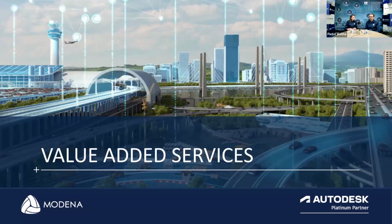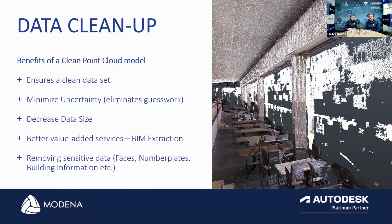If I can just add on that part of cleaning in Recap specifically: when you remove point data, for example if someone's face was scanned, when you remove that information you save, you can update the photographs as well to completely remove that from the data. So not only the laser scan data, you can remove sensitive information, but the photographs as well. Also in the pictures, yes. That's a feature that Recap added fairly recently, which is a very, very useful tool to remove that sensitive content out of the photographs as well.